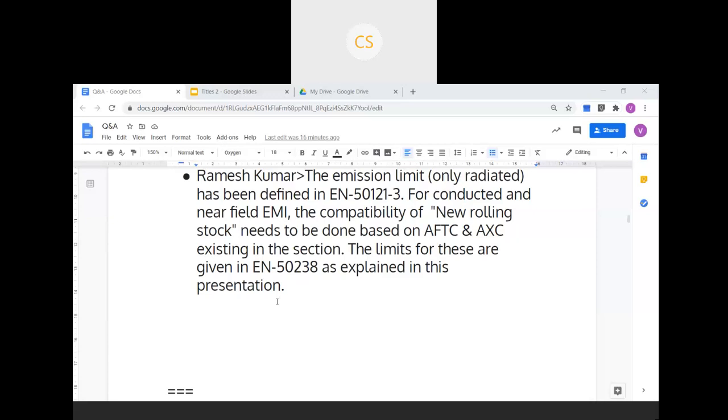So we have to see this as a holistic, integrated approach, and space has to be designed. There has to be cabling, for example, where the signaling cable has to go and where the power cable has to go, and then it has to be laid. Cable harnessing has to be thought of and made in the initial stage of design of locomotives. Otherwise, it comes along the way, running the power cable over the control cable and causing interference, EMI. All these problems are coming.